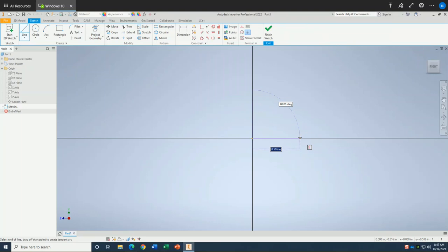So that's going to be a small size house, but pretty much all the components of the house are going to be there. When I move my cursor to the right, keeping it as horizontal, flat and level as possible, the computer shows me the dimension length of the line. Because it's highlighted, I can type literally 3, because I want this line to be 3, enter. So that's the 3 inch.